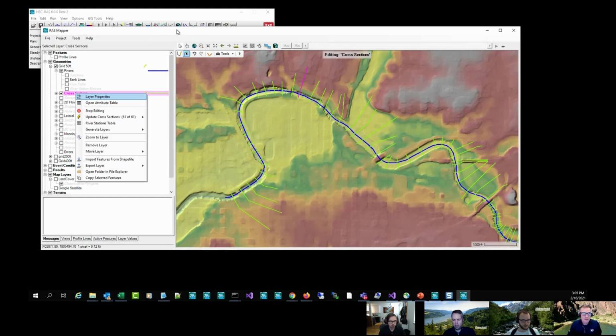So with that auto update turned on, Cam, you could make that change, extend your cross section out, and then simply go File, Save, close out of RASMapper, and recompute. That's exactly right. And it's going to have all those changes automatically enforced. That's exactly right. So that's cool.